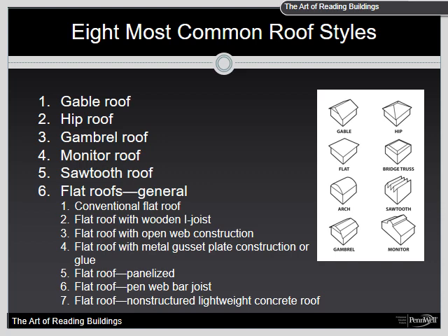A variation of the gambrel roof is the mansard style roof. The difference in the two is that all sides of the mansard roof share a hip style slope. Much like the difference between the gable and the hip roofs, the gambrel roof has flat walls that rise to the peak on opposite ends, whereas the mansard has hip slopes on all sides that rise to a secondary slope from the ridge top. A mansard roof is often characterized by dormer windows that protrude from the steep slope of the lower pitches.